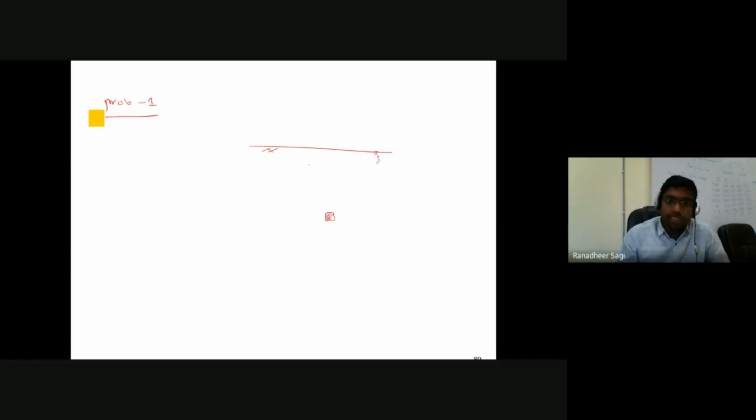and it is said that the total normal stress the soil sample is subjected to is 200 kilonewton per meter square, and the pore water pressure developed in that soil sample is 80 kilonewton per meter square. What is additionally given is the effective shear strength parameters of that soil. That means c dash and phi dash are given. So the c dash value of that soil is 16 kilonewton per meter square, and the phi dash value of the soil is given as 30 degrees.